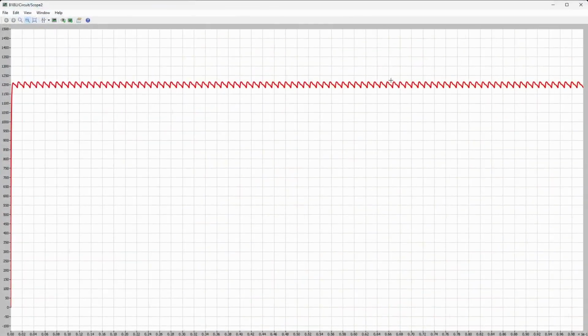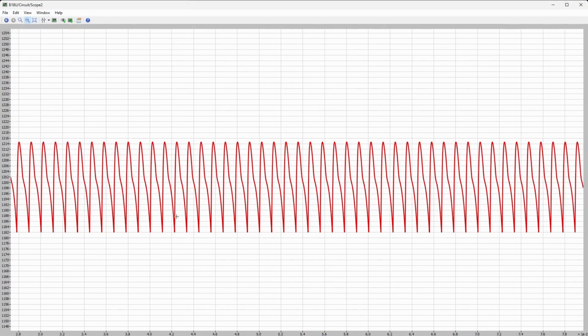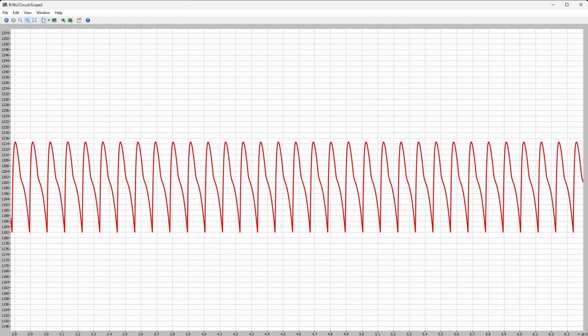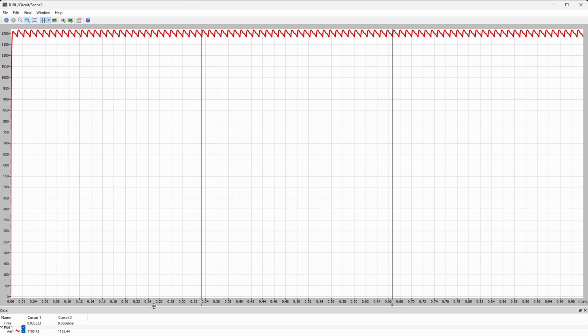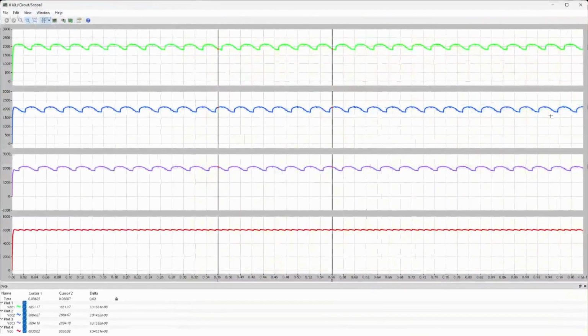If we now look into the current, we will see the ripple current here. Again, this depends on what type of application we have. If we measure the DC current level here for our 5 ohm load, it's 1.2 kilo amperes. It also has the same number of pulses in a space of 20 milliseconds. And these are again the voltages. As we can see, the effect of current flow and the effect of source inductance are both reflected on the respective curves.